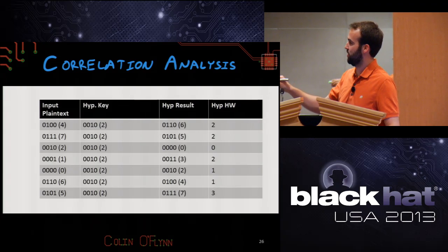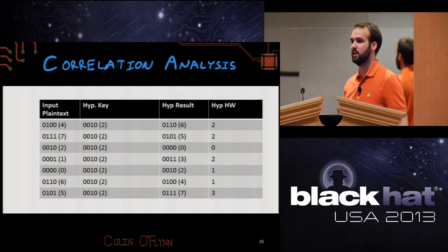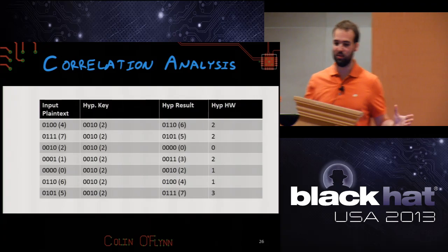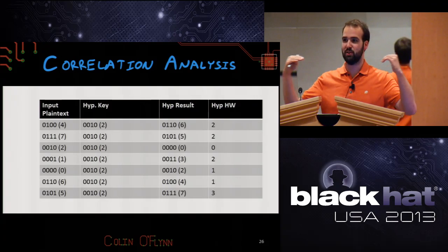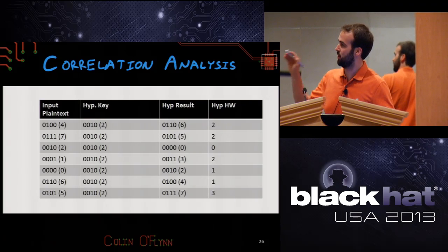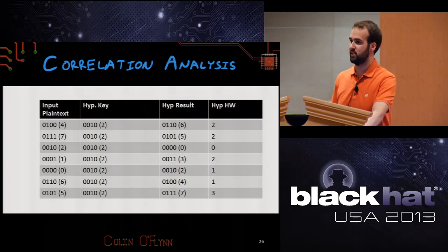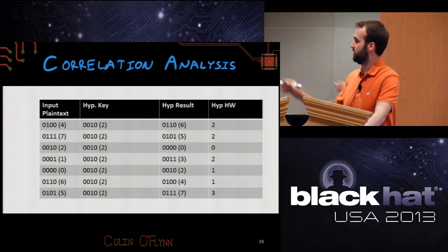And why I have so many traces: here I have 7, in real life, I was showing 50, it might be thousands, is that over time, everything else becomes noise. Everything else just becomes white noise and effectively goes to 0 when you're looking at the correlation, but the data you care about, even though it may only be 8 bits out of 128, creates this huge spike.